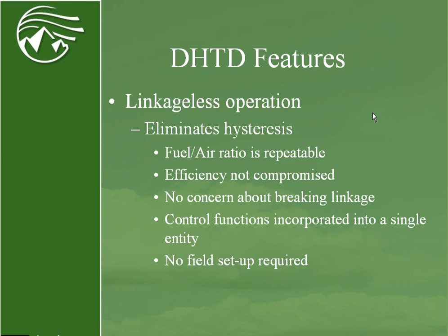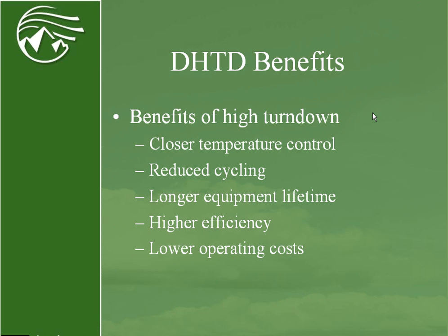Usually a mechanical linkage system is based on an actuator, so you have your valve and then you're cut off to the blower. And these two things, the gas valve and the blower, can actually get out of sync, and therefore you're not matching your inputs. And they can actually get out of phase. So this is a linkageless system, so it eliminates that. It eliminates the hysteresis, so you're not cycling your system or jumping up on your loads, and your efficiency is not compromised. And there's no additional field setup for the system, so that's really nice.